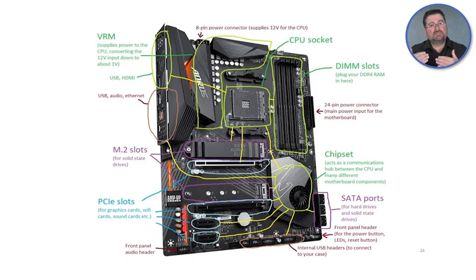So depending on the type of RAM that your motherboard requires you to use, there may be a different number of keys and notches on the RAM itself. This way you don't make a mistake and try to insert RAM that cannot be supported on your motherboard. So these DIMMs are, in another term, keyed. Keyed meaning you can only put them in one direction and they only accept the correct type.